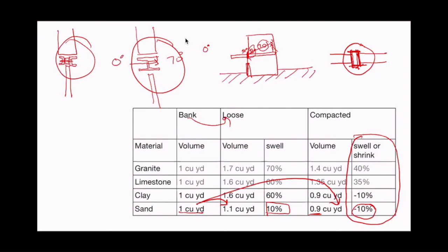I see, now you've got me saying them back and forth. The goal is never to get zero. There will always be thermal bridges, like the diameter of a bolt or a nail or something like that. We don't worry too much about that because that's almost impossible to deal with.